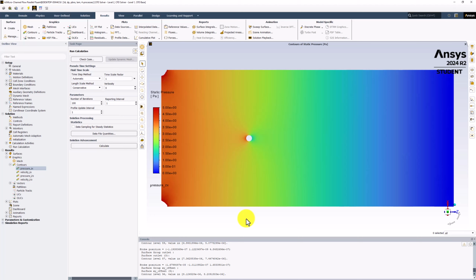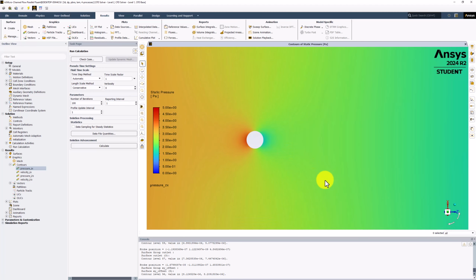In front of the cylinder, we can now more clearly see that the pressure increases slightly as the flow is slowed, as predicted by the Bernoulli equation. Unlike the velocity contours, however, there's no symmetry between the front and rear of the cylinder. As the fluid moves around the obstruction, it experiences viscous losses that decrease the pressure. This is not accounted for in Bernoulli's equation, leading to the discrepancy. This creates a low pressure region behind the cylinder that produces a net drag force on the obstruction.